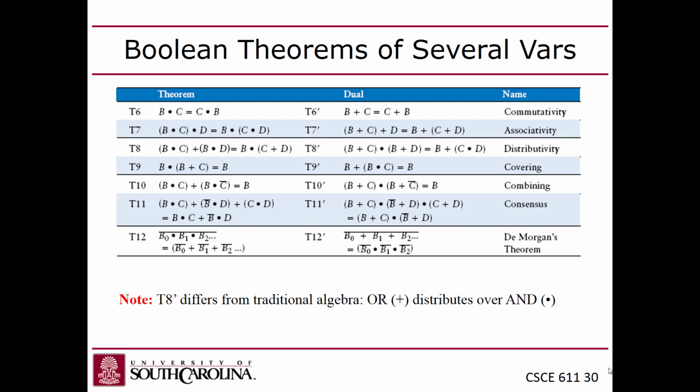Now, it makes sense doing it that way. Looking at it, it's confusing. It doesn't seem to make any sense just looking at it. All right, and then De Morgan's theorem is when you have an implicant where you've got literals that are ANDed, if you complement that whole expression, then you change the ANDs to ORs and you complement each individual literal or variable in there.